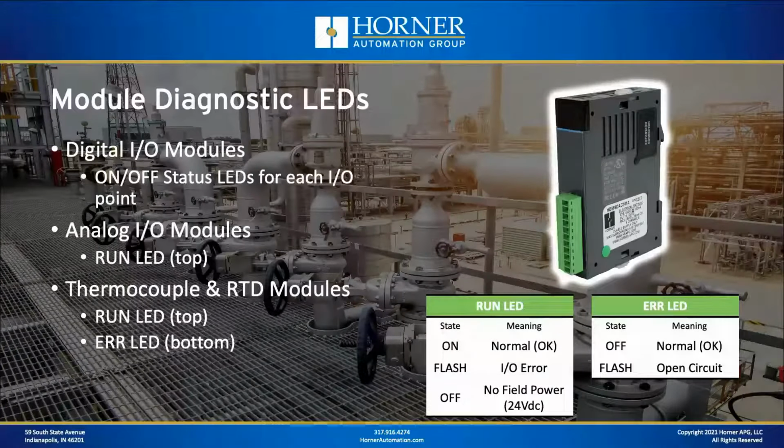Now, some modules, specifically thermocouple and RTD, along with a mixed analog module, also have an error LED. And that light is off if everything is okay, and it's flashing if you have an error. Now, what is the error? For thermocouples and RTDs, it's going to indicate an open circuit for the sensor.